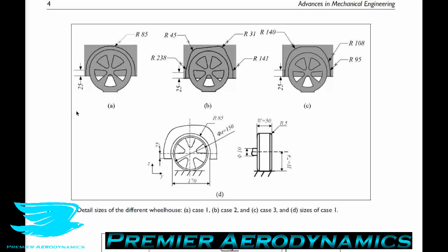So the Audi produced the lowest drag coefficient of 0.4225 for the armored body it was put on, while the Toyota had a drag coefficient of 0.434 and the Mercedes had a drag coefficient of 0.442.